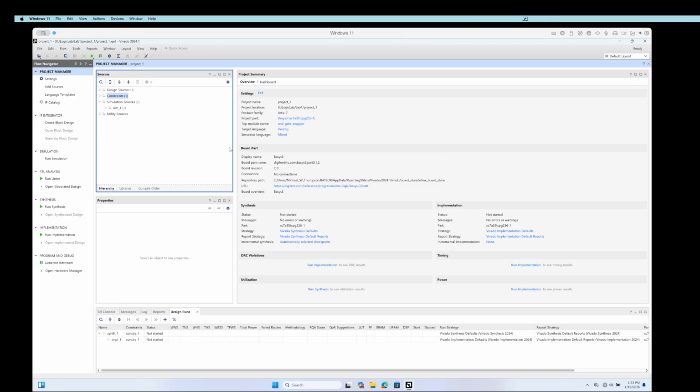Okay, so now I have everything in the project, and we're not really worried about the actual code yet. I'm going to have you do a code completion so that you'll know what to do and see how to edit a file. But this is ready to run a test bench. We have our design put in, and so we can look at this left-hand column that shows what the different steps are. We've added the sources. We don't need this step because we've already made our design, and now we're ready to do simulations.